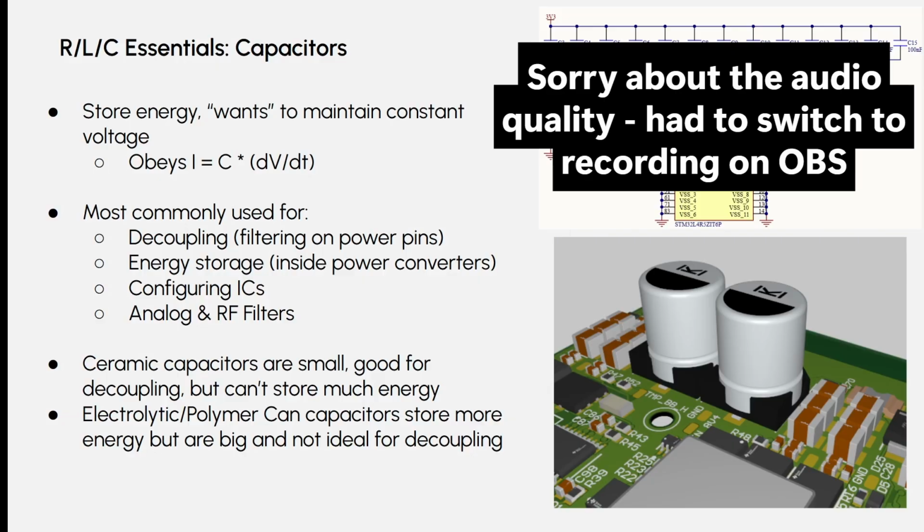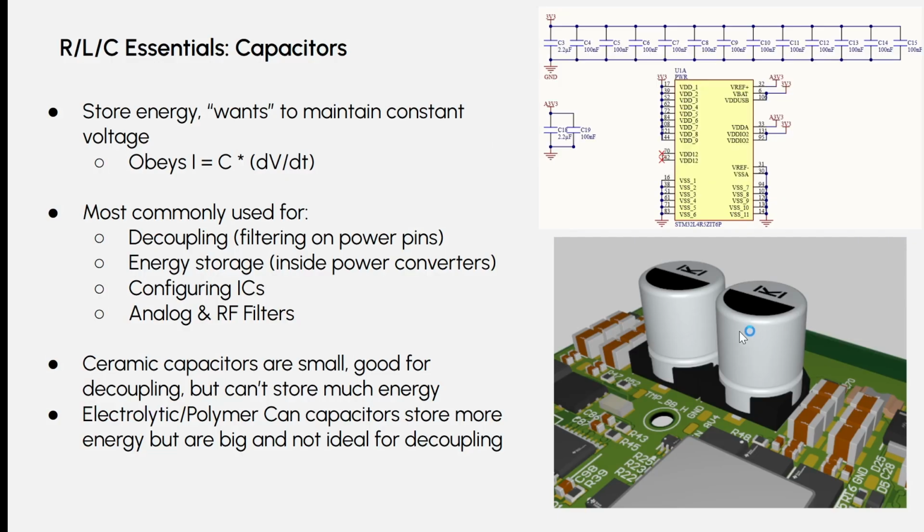Yeah, capacitors good for decoupling. Ceramic capacitors are typically used for this. As in this image, you can see the ceramic capacitors are the little brown and gray guys. And then you have what you've usually seen as a capacitor, the electrolytics, these big guys. They have different purposes. Generally, we don't use the big electrolytics except for very specific power applications. The ceramics are more than good enough for digital electronics.